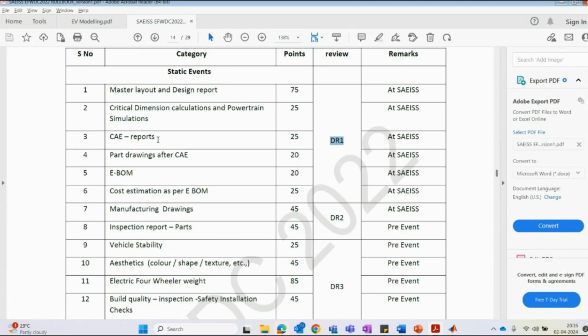There are simulation tools that don't tell you that your member is going to fail. So you are the one who should know the Young's modulus of that member, and if this is the stress acting on it, it probably is going to be a catastrophic failure. So do it, and also understand how to read the data coming out of the simulation. And the report, ideally, should not be just images of a colorful plot.